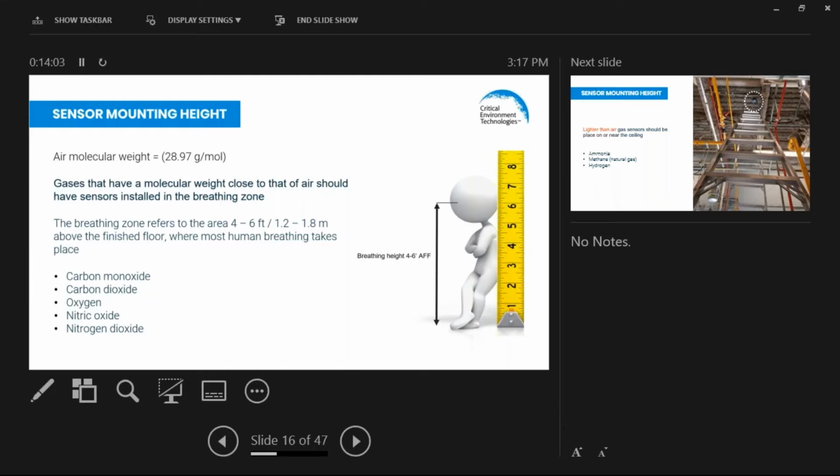And each and every manufacturer of those sensor cells publishes this data. So this data is available. So whenever you're thinking about having sensors in stock to meet a particular requirement for backup or for add-on to an existing system, you want to look very carefully at the time it would take to get delivery from our factory or from the gas detection manufacturer's factory, and the manufacturer's data in regard to shelf life.